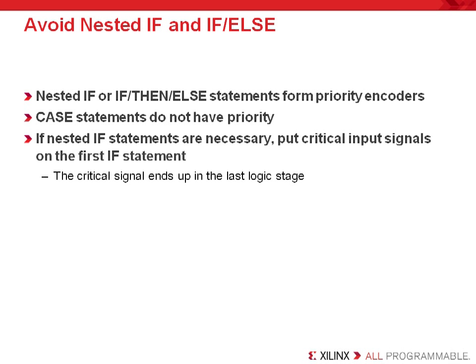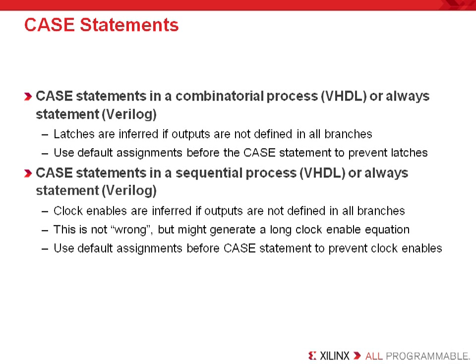If the last example was constructed with 4 input LUTs, it would require only 2 logic levels. Recall that the function had 9 inputs, which would require 2 LUTs in series and a total of 3 LUTs. So see if you can make that work and replicate what we expected and how the difference would come by using a case statement. Case statements are almost always the way to go when muxing logic.